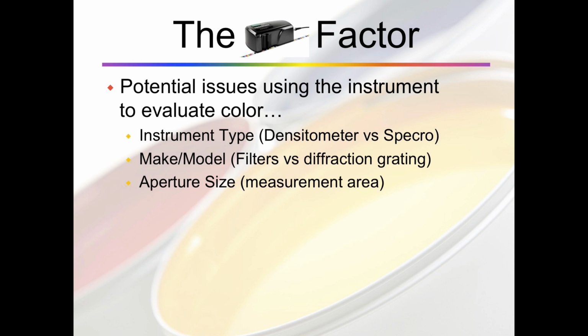But what you need to know when using that size aperture is that it opens up the opportunity for more variance in the measurement. The instrument has less reflectance to work with at that size, and you may see more variation in the measurement when using a smaller aperture size.